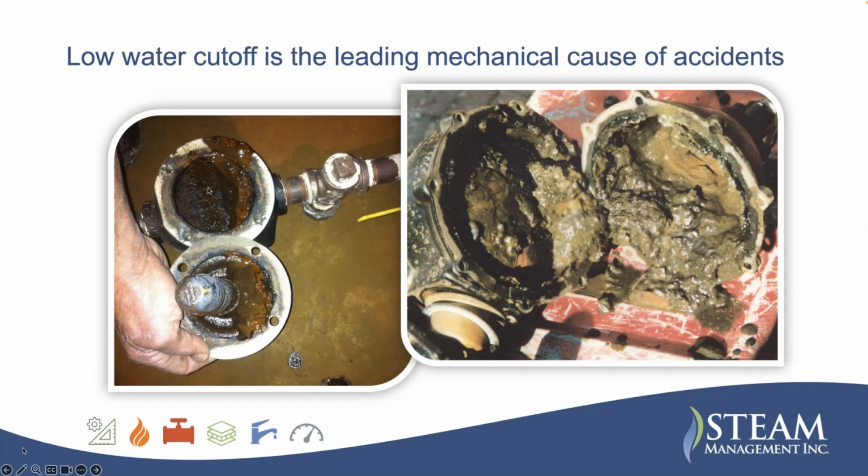Now this one, a friend of mine installed in a church in West Virginia. He sent me this picture on a Saturday night. This boiler was only about 9 months old. They had just replaced the boiler before it dry fired, and they never blew down the system or anything. So the insurance company paid for the first, and they told the owner they were only going to pay for half of the second because they did no maintenance on it.